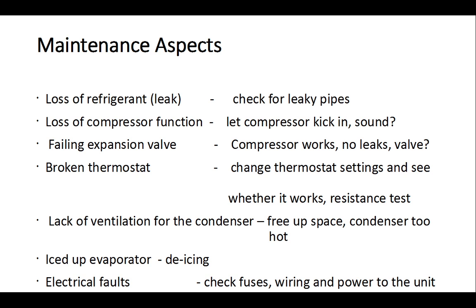So if a fridge goes down, first I would try and see whether the pump is actually working. Does it make some noise? If it doesn't make noise, there's a good chance that there's an electrical fault, or maybe the pump itself has gone down, like the bearing is gone or something, that is a mechanical fault. If the pump is working, then a chance could be that the refrigerant is leaking. And if the refrigerant is not sufficient and it can't pressurize sufficiently, what you may find is that the inside of the fridge gets warm as well as the outside. The whole process doesn't work anymore because the pump can't build up enough pressure.